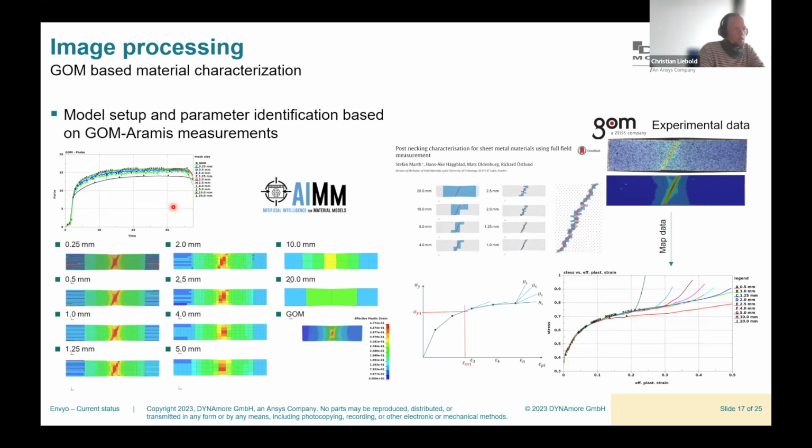And we've also been working on other methods which try to identify crack paths, and then, through iterative steps and deformation of only the crack path elements, help the user to identify a plasticity curve based on different element lengths. So if this data is being mapped, then you can do the same thing for different element lengths as well.